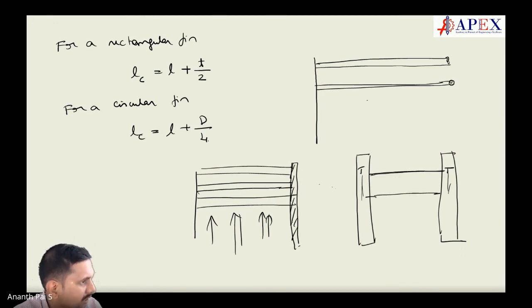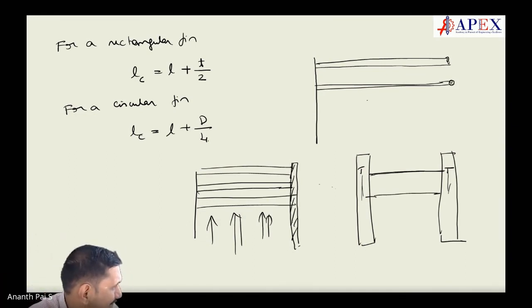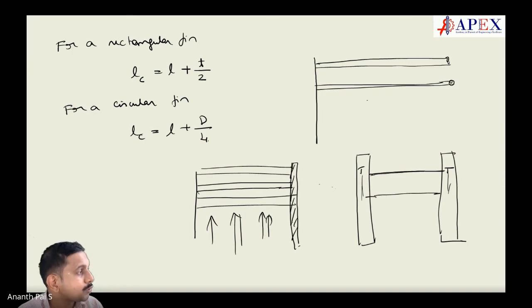Sorry, the last case, the fourth case, is the general case. There it is not of uniform cross section. What they use is a tapered cross section. You see that? So it increases complications in design, but otherwise it is good, because you need air to reach the bottom position. That is why they use a tapered fin. The angle is also very important. Everywhere the calculation is important. Optimized one. Where you keep the engine is very, very important. How it is cooled is very, very important. Actual fins, these are all actual fins.